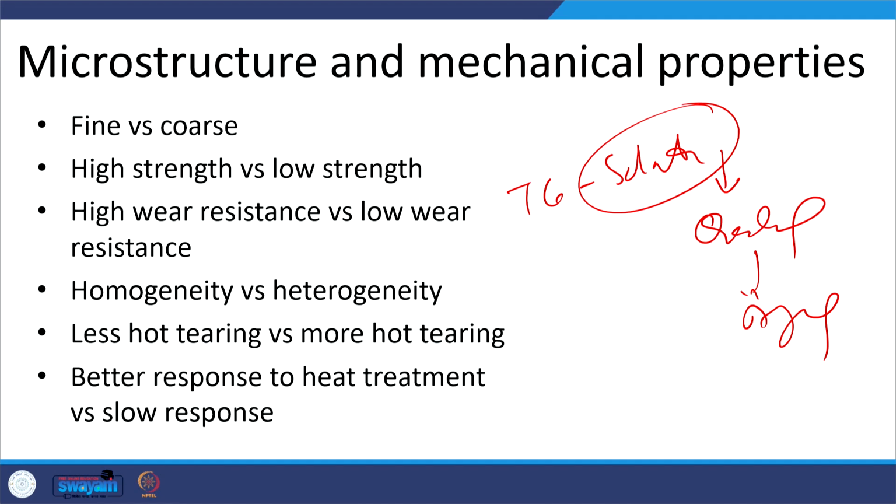The same is true for other ferrous metals, where austenitizing is followed by imposing different cooling rates as per the need. Austenitization also takes a longer time for the coarse grain structure compared to the fine grain constituents.